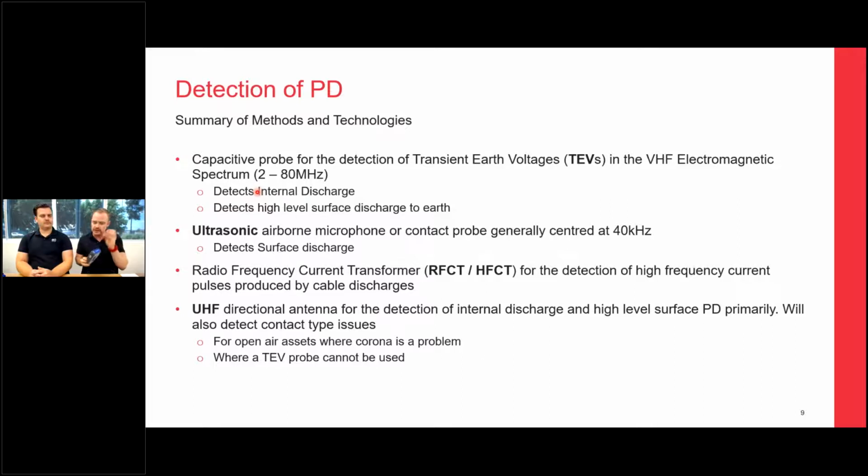It will put it on that screen, and then the analyst, such as the PD surveyor, the user, can then go from there and figure out if you're detecting PD. The second way that we detect, firstly, TEV signals are more inherent with internal void PD. So when we have internal void, the best way to detect them is TEV.